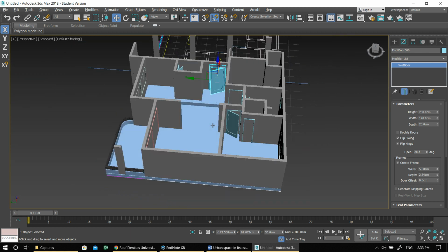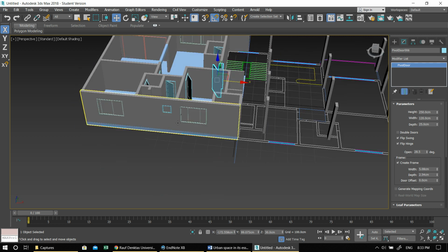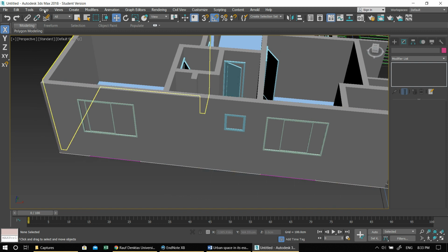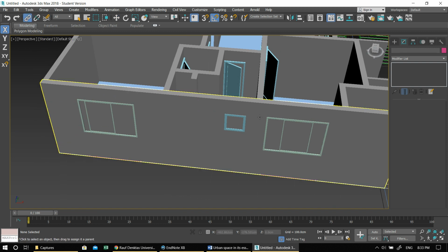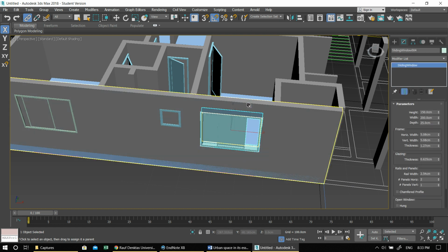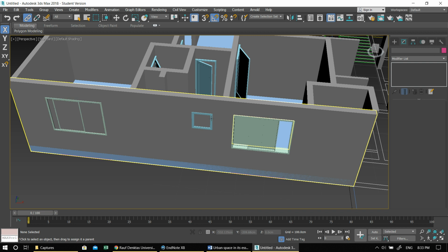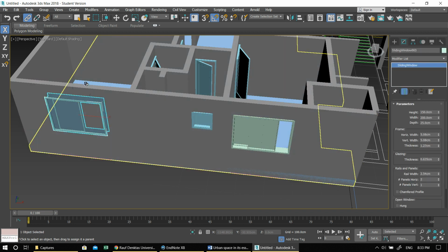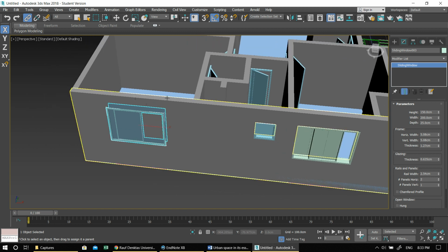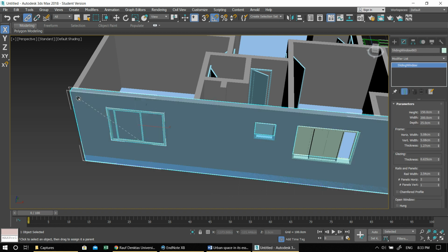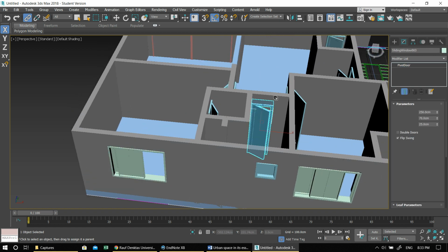I'll go ahead and start removing those from the walls. The way to do that, I'm repeating again: click on the link, don't click anywhere, wait for the window to get outlined, then drag and drop it on the wall. Nothing selected. I'm selecting elsewhere just to make sure that nothing is selected. You see, now I selected the slab, so it will not work. Window, make sure the wall is selected, it will be open. Okay.